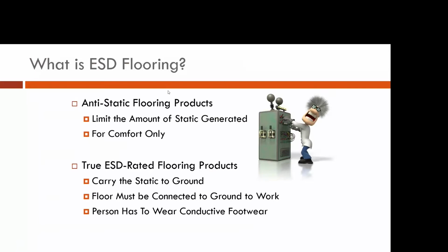So a big difference, because when we talk about things like conductive and dissipative, which we will get into, it's always dissipative on the bench top, but the floor could be conductive and dissipative. So again, we'll get into that as we move along, but that's the major difference. So if you're dealing with ESD on a bench top, it's vastly different than the flooring.